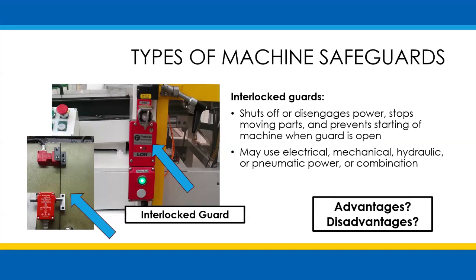Advantages of these guards are they can provide maximum protection and they allow access to the machine for removing jams without time-consuming removal of fixed guards. However, the guards require adjustment and maintenance, and they may be easy to disengage or bypass.